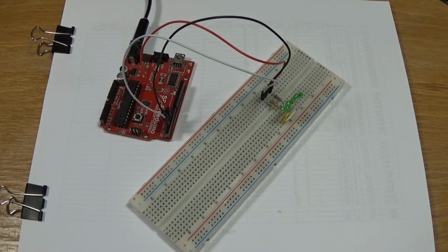And so I used a delay function to give you a bit of time in between each LED so that I could actually see them blinking on and off like this. Now, I used a very wasteful delay function which simply uses up all the resources of the microcontroller for the time that you're delaying for. In this case it was about 500 milliseconds, I believe. And so the microcontroller can't do anything else except service interrupts.